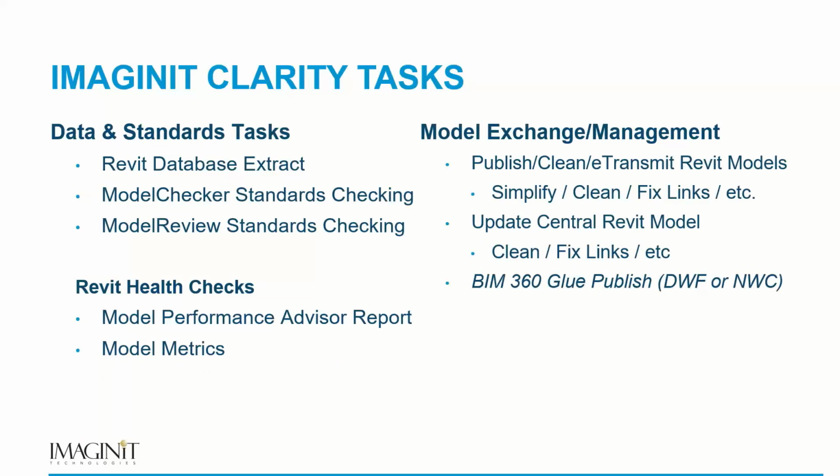We've got tasks that are related to data and standards, like getting data out of Revit and into a project database, or checking standards with either the Autodesk Model Checker tool, or the Autodesk Revit Model Review tool. We support both of those to automate the checking process overnight. We do a lot with Revit health checks.